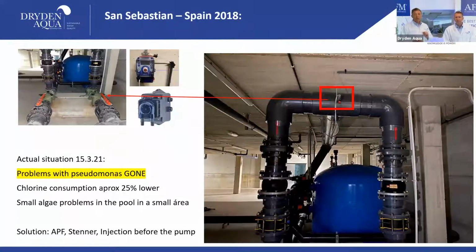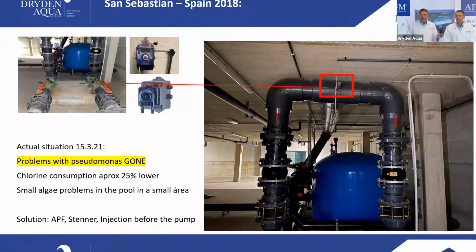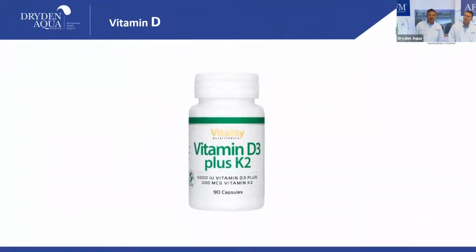Why reduced and not gone, maybe? That's a good question. Well, because of the UV medium pressure. Jan, I didn't tell you this yet. Why? They have a UV medium pressure, and we learned in the last session, the UV medium pressure will oxidize the combined chlorine to nitrate. And nitrate is a fertilizer. So the best would be take this UV medium pressure out and go for Advanox. That would be the perfect solution. So you see, we are really up to date. Okay, that's the last one.